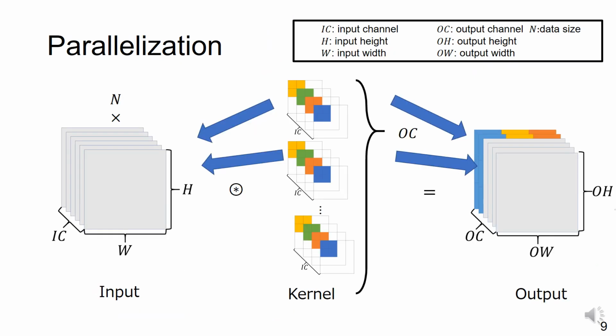In this work, parallelization along the output channel is applied to speed up the execution of the ODE block in the PL part. This figure shows an example of a two-parallel case. Convolutional operations compute each kernel sequentially for an input. Since the input does not change, the computation of multiple kernels can be executed in parallel. In the figure, two kernels are calculated in parallel, so the results for two channels are obtained simultaneously.